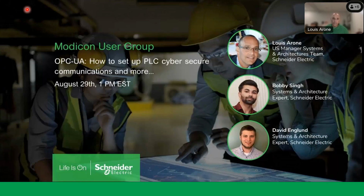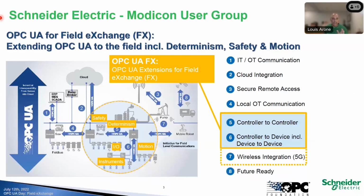But before we get there, just for clarification, I grabbed this slide from the OPC Foundation. It basically goes over all the uses of OPC and what they're working on. As you can see, there are lots of uses for OPC. Typically, OPC communications has been between SCADA and PLC. Today, we're going to talk about SCADA and PLC, encrypting that. We're also going to talk about PLC to PLC using OPC UA, which is kind of something new. Normally, you don't associate OPC UA with controller to controller.